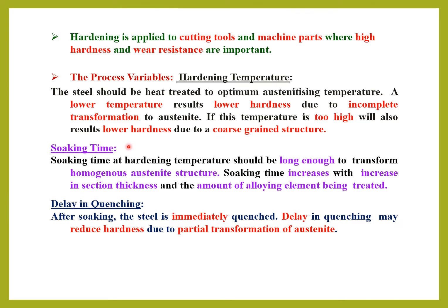And then soaking time. We have to wait for some time after heating the material to high temperature, to give time for transformation. Next is quenching.